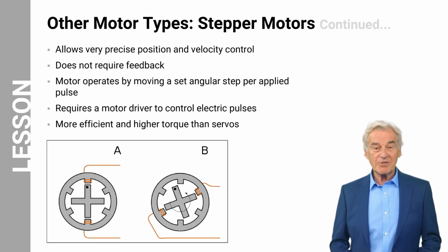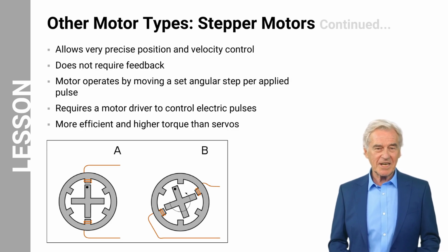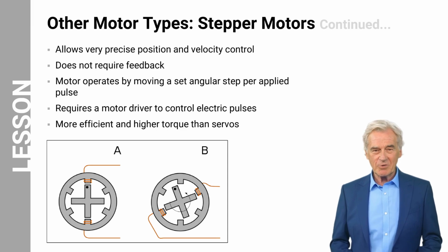This diagram illustrates the operating principle of a stepper motor. Stepper motors achieve precise position and velocity control by utilizing a series of discrete electrical pulses. These pulses sequentially energize different sets of stator windings, creating a rotating magnetic field. The rotor, in response, aligns with each successive magnetic field generated by the stator windings. While the diagram shows only 6 stator windings, practical stepper motors typically have more, allowing for finer position control with a smaller number of input signals.